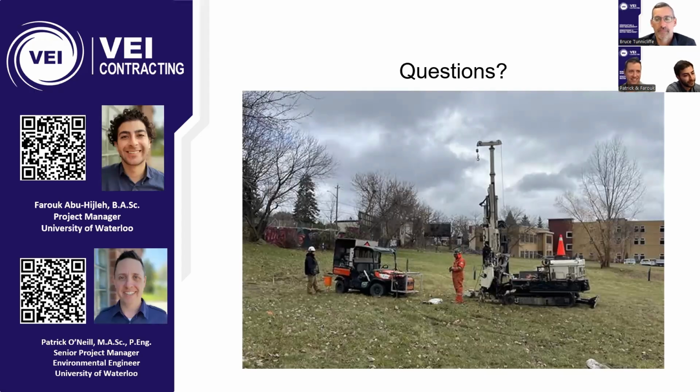It also says it might appear, maybe you can comment on it, that the HPT provides more accurate assessment of the K value, perhaps with more information per vertical meter. But as such, do you think that the factor of safety usually applied in dewatering could be reduced? Like in the overall picture, could you use it and then perhaps have a lower cost estimate when you go into a job? Yeah, and that's why I brought in the idea of system design, not just estimating Q, because it doesn't end with just getting the Q. You have to build a system that can handle those flow rates, right?